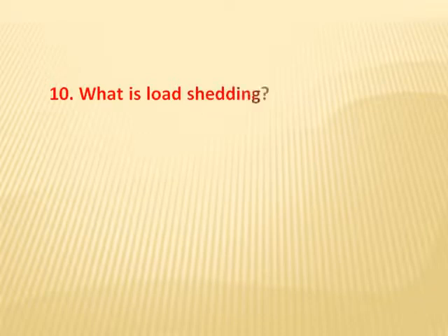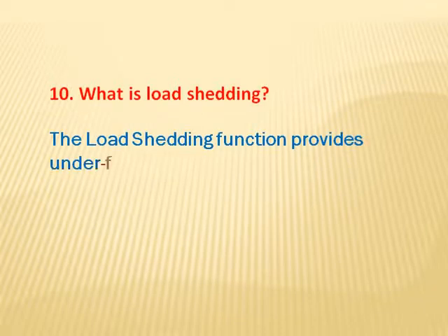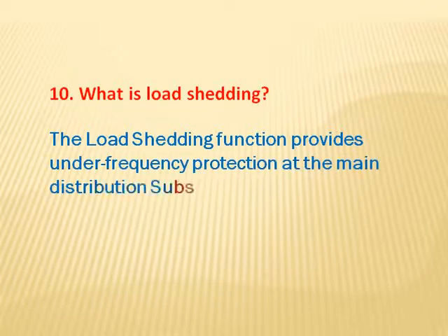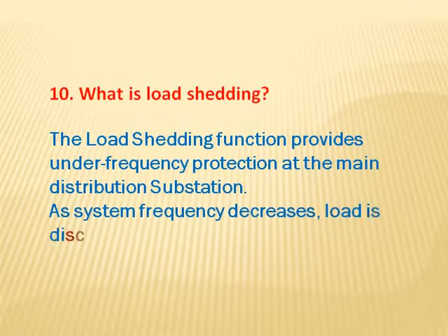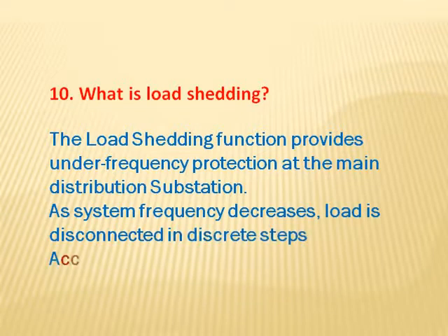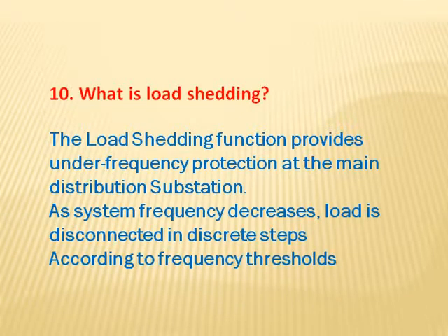What is load shedding? The load shedding function provides under frequency protection at the main distribution substation. As system frequency decreases, load is disconnected in discrete steps, according to frequency thresholds.